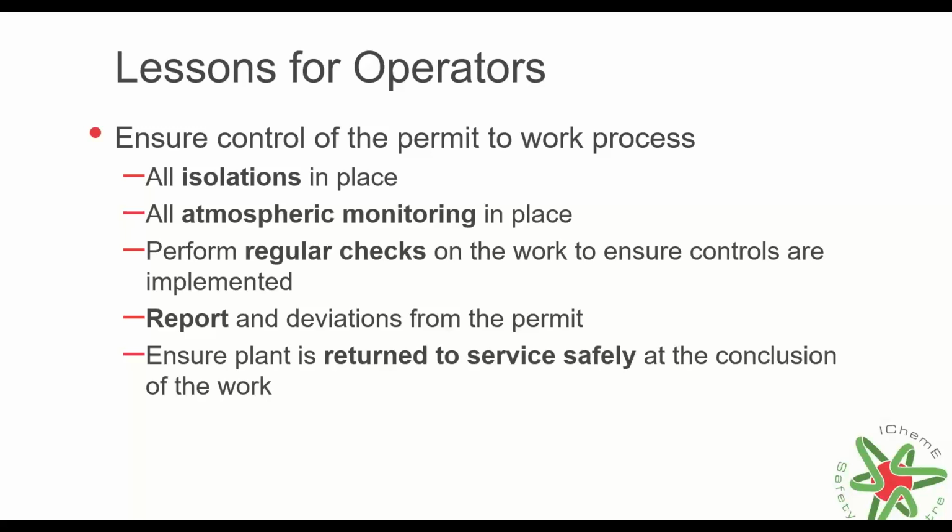Do I need to do it here? Can I remove the work to a safe area? In some instances, this is possible, and you may have safe work bays where you can undertake hot work safely within a facility because there are no flammable atmospheres around it at all.